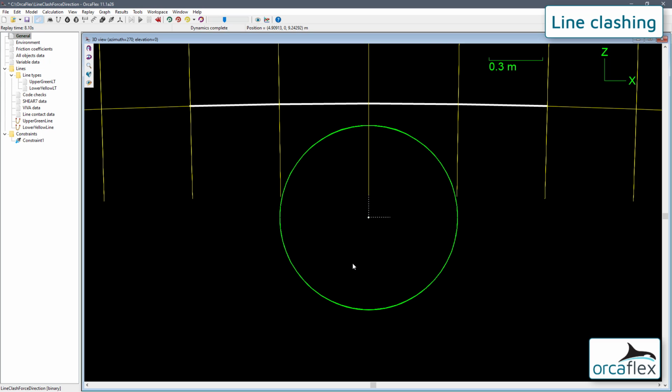This has occurred because, with a longer time step, the distance between node equilibrium positions is greater. Consequently, the green line centre line has, from one time step to the next, moved far enough that the yellow line centre line has effectively swapped sides and is therefore no longer being correctly modelled.